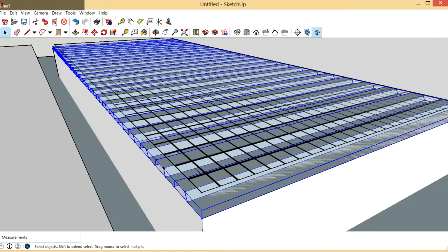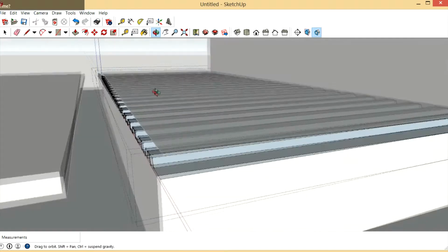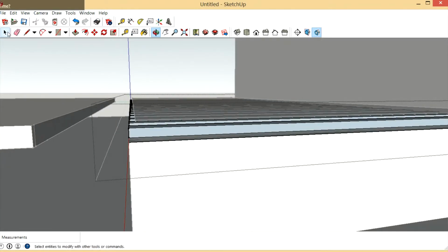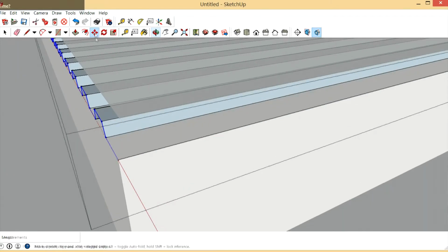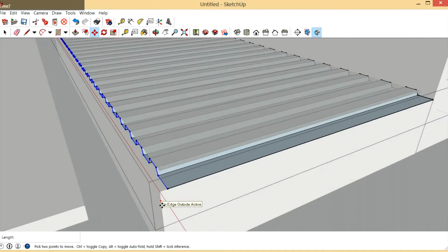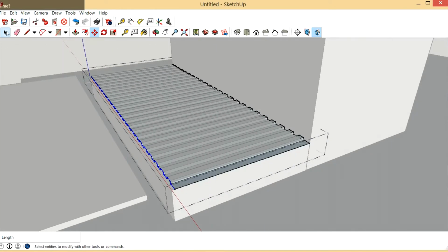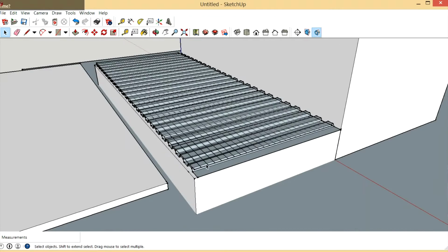If I was going to select my pan, I would select all of the ends like that, and then I'm going to pull them back about 3 inches so that you don't see them, something like that. And then your concrete, because you don't want any kind of metal in your concrete near the edge, because it will rust out and bleed out.